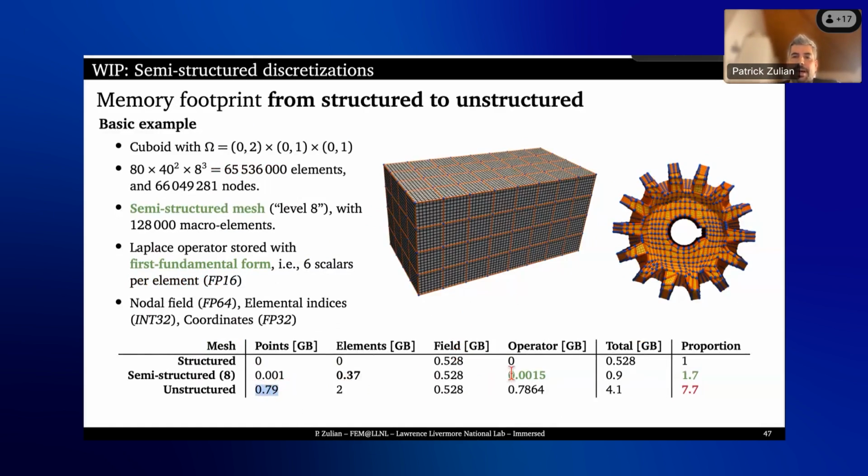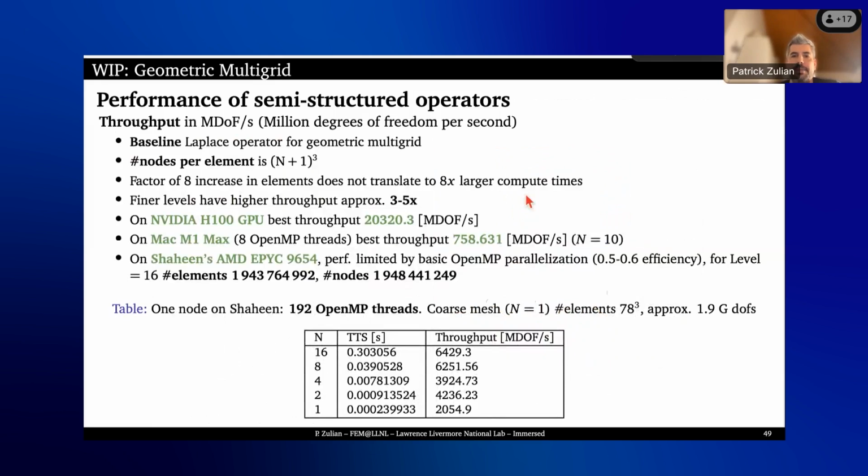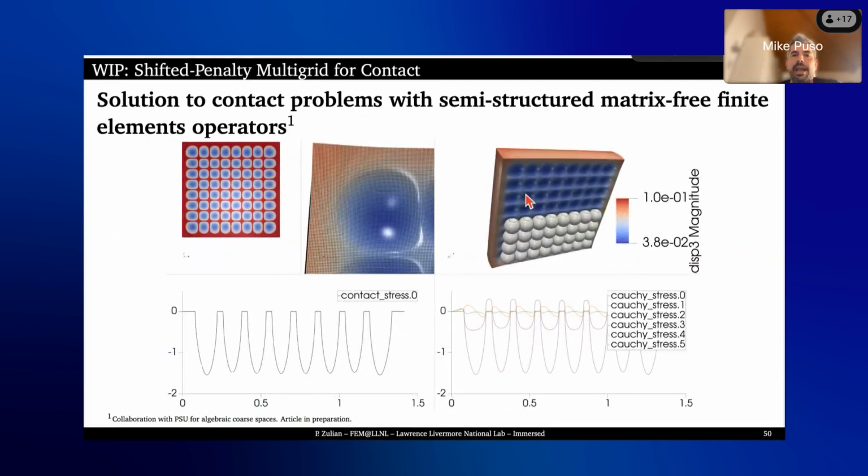For example, for the elasticity part here, I only store the adjugate and the Jacobian determinant, at least for the preconditioner, and then for the actual operator, if I have an isoparametric version, then I have to store the coordinates. So there's no way around it. Any extra term you have to store, of course, you will have to pay the price for it. But you have to pay the price anyway if you do matrix free.